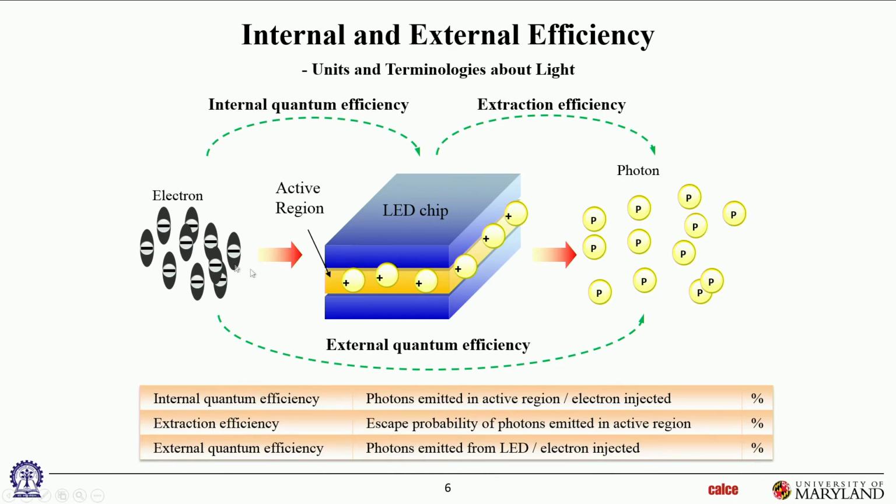Basically, in this one, he's simply saying you supply power to the LED chip, and electrons are basically helping recombine the internal charge carriers and emitting photons. So you know how much electrical energy you're putting into it, and you know how much light is coming out. Again, that's why the units of measurement are important. That's called radiometry or photometry, where you measure how many lumens, how many luxes, how many candelas. That's how you measure the energy coming out. And knowing the energy that's gone in and the energy that's coming out, you can calculate efficiencies.